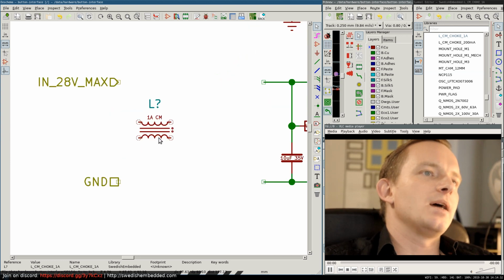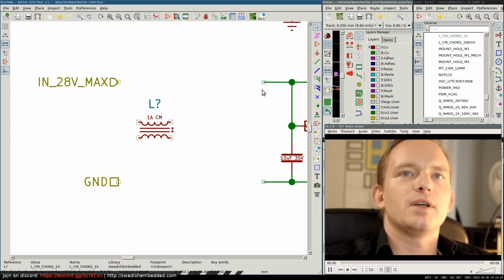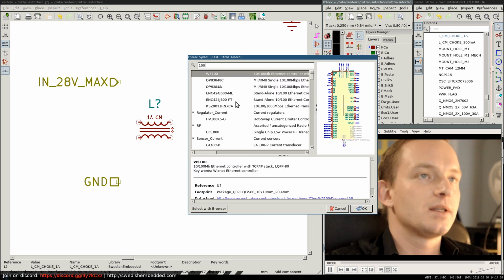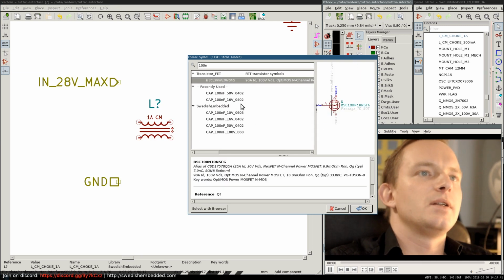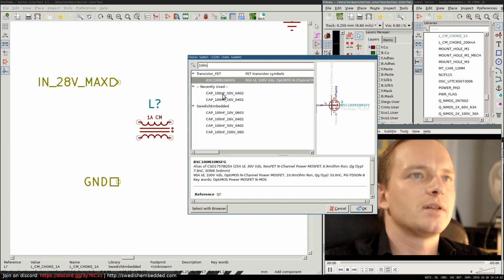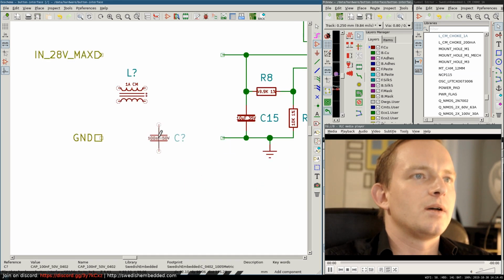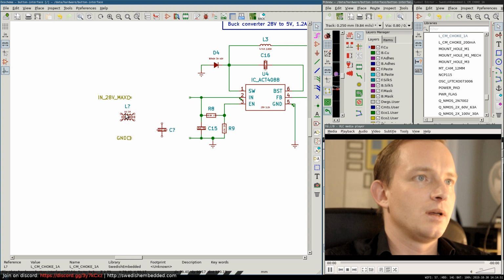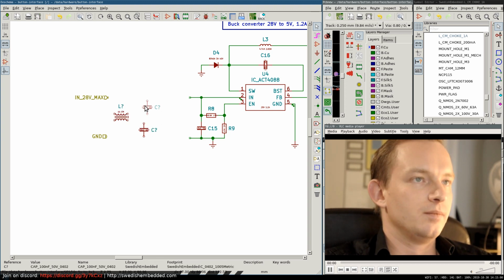And to do that, we have to put two capacitors here. So we can do like this. I can choose a 100 nanofarad capacitor, and I can put it here, and another one. Let's see. Put this one here. And I can put another one there.